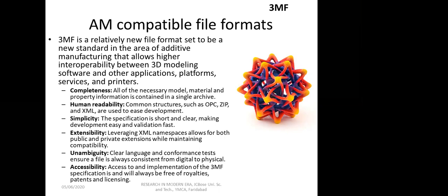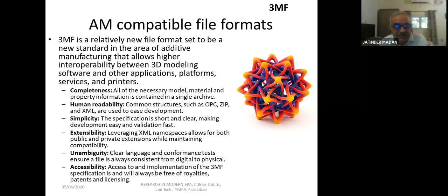Because you have to move through this chain from the CAD model, you need conversion, and then certain applications. The 3D printing companies will provide you some kind of software which will convert the CAD model information or STL model to the printing format. We will see in the next few slides what the process flow is.